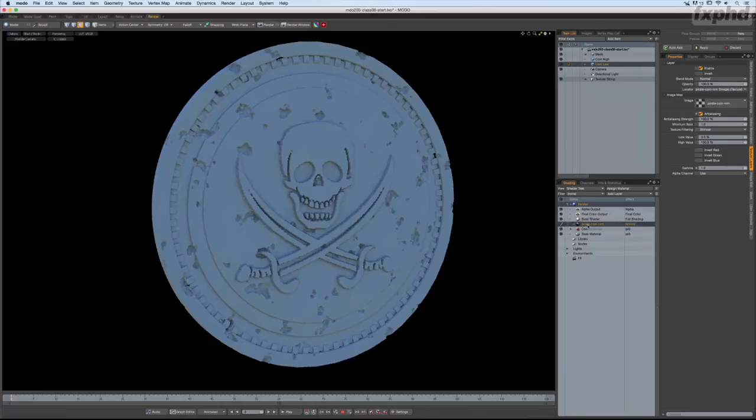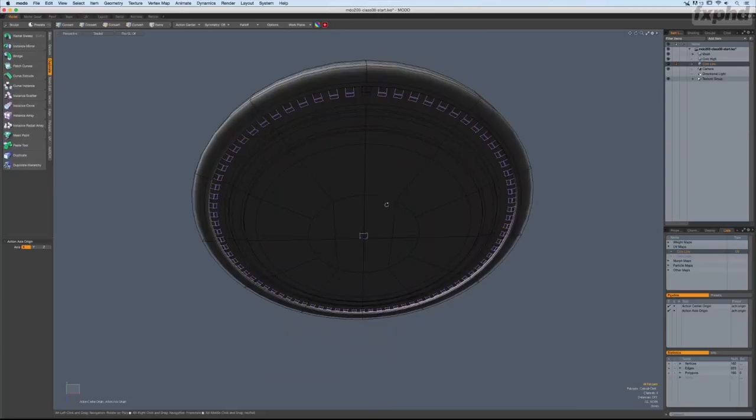So we're going to make a small change. Let's do the whole baking procedure again. Bake from object to texture. And then this time, we have to put a distance. And this is how far the ray is going to go before it turns around and looks back down at the model. Now, this is a moving target. Depending on the size and the scale of your scene, you're going to have to figure this out.